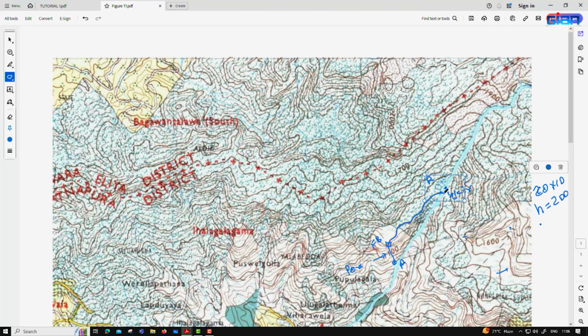So, we could have come on the left bank also here like this, and somewhere here and gone down. That is also a possibility, but the choice depends upon availability of roads, availability of land, easiness of transportation, right. So, depending upon those things, we will select which bank to construct our canal, penstock and powerhouse, right, canal, penstock and powerhouse. I hope this part is clear to you.